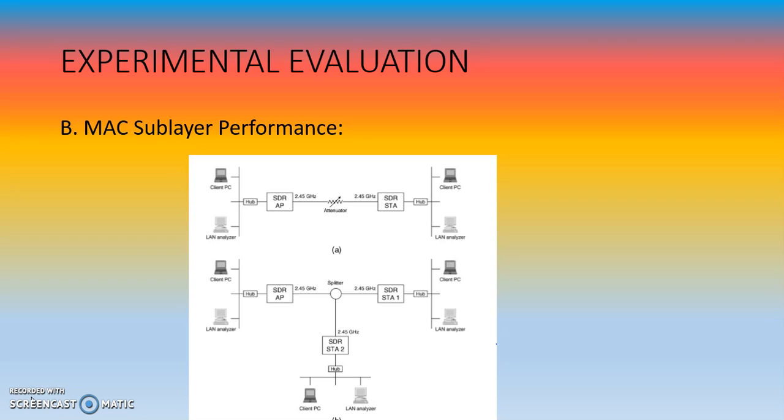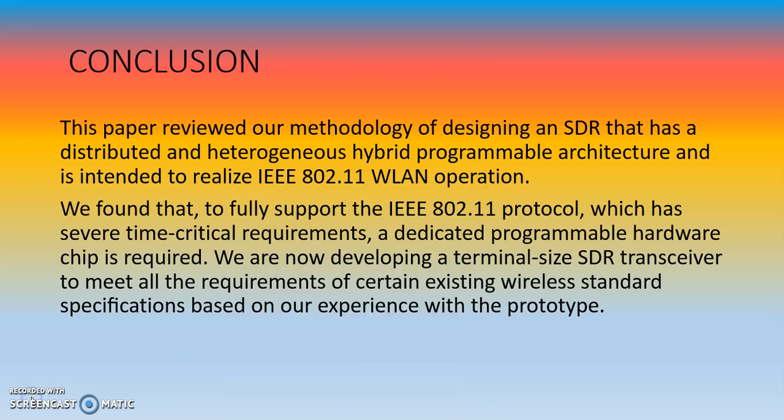At the SDR transmission set, the Ethernet frames received from the Ethernet IF were converted into IEEE 802 frames without a frame check sequence and then transmitted to the DSPs via the VME bus. PLCP frames were first generated by adding the FCS, PLCP header and PLCP preamble in the DSP and then writing them into the first-in first-out buffer in the DSP board.